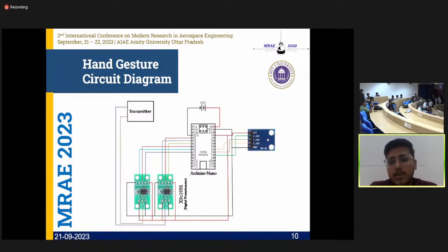That data is then transmitted to the Arduino Nano, which processes it, and we have written a code with a marginal error value, in case there are any jitters or flickers, so that will be our error range. Even if my hand moves, because you can't keep your hand stable at 180 degrees all the time, we have taken an error margin of 30 degrees on both sides, that is 150 to 180. If my hand is between that, it will be in a stable condition.